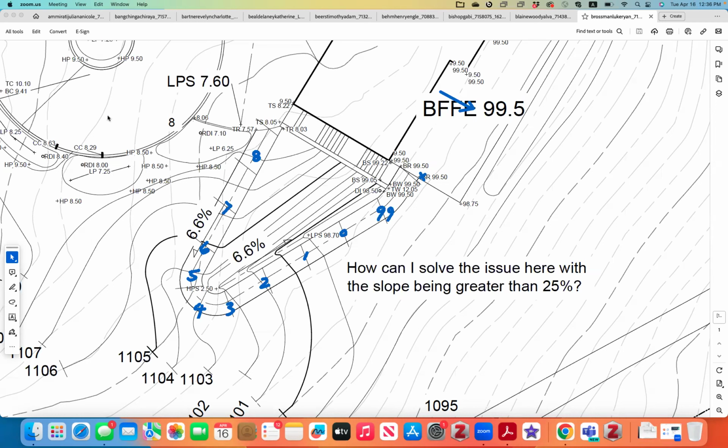If this is okay. Honestly, I wouldn't have the ramp extended here. I would have the bottom of the ramp here, right? Because this is where you land from the stairs. You're coming down from the stairs. This portion needs to be part of the back plaza. All right. This needs to be part of the back plaza. Does that make sense? You do not want this area to slope like that and then also slope like this. They conflict with each other, right?